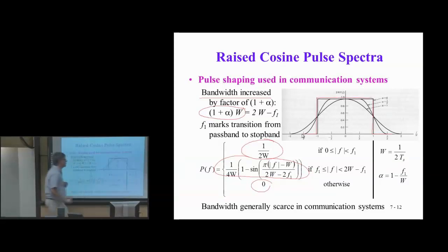For the frequency response, when alpha is 0, what we expect to see is the Fourier transform of the sinc. Alpha of 1/2, the bandwidth increases by 1 plus alpha, which would be 3/2 in this case. The plot here is normalized. It's F over capital W, the bandwidth.